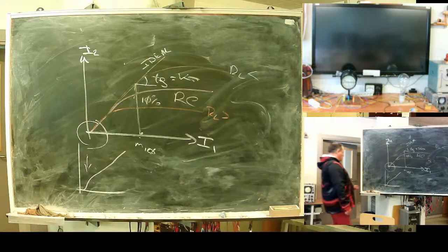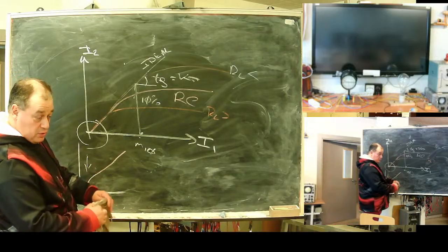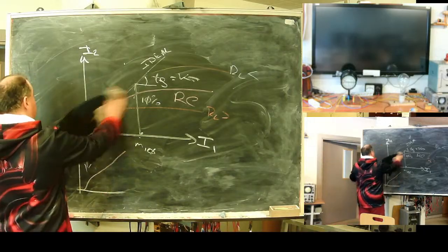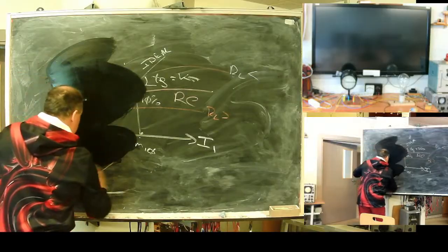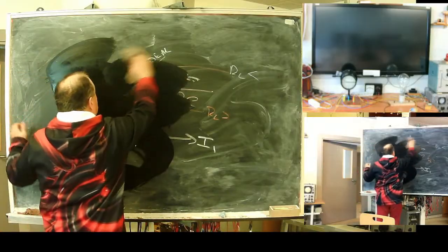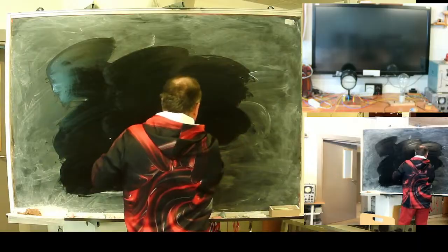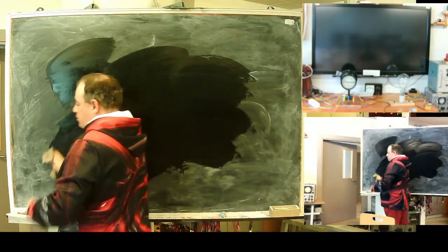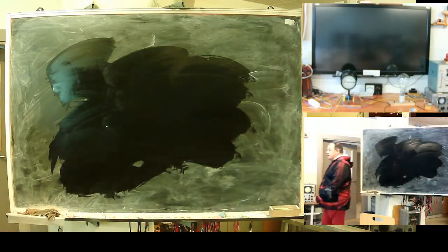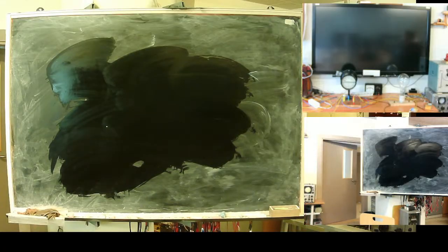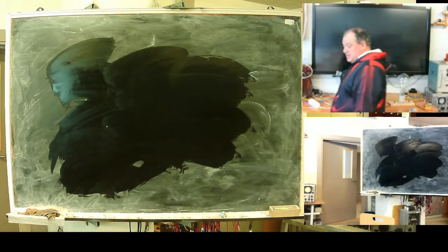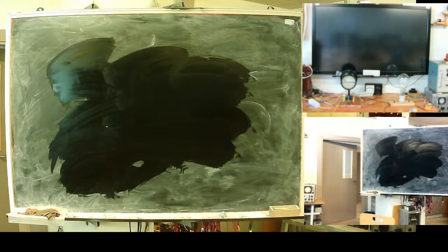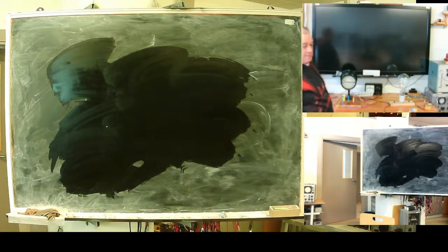When you're looking for an input current transformer, you start with what? With dynamic range. First, you need to understand there is a huge difference between protection oriented signal channels and metering.